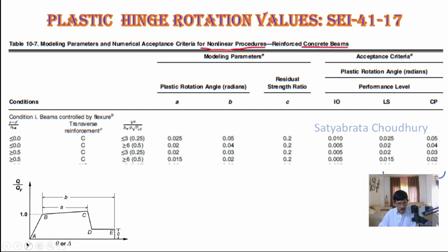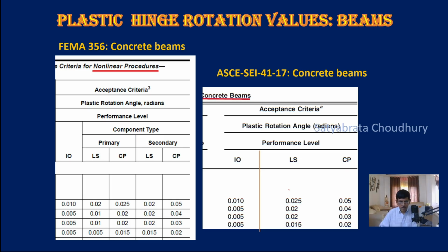Again, remember the post-deformation curve, with the normalized vertical ordinate like this, where segments ABC are available in the code, and the point C is something like collapse prevention, point E is something like final collapse. Now let us see further.